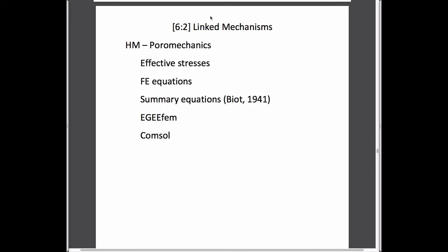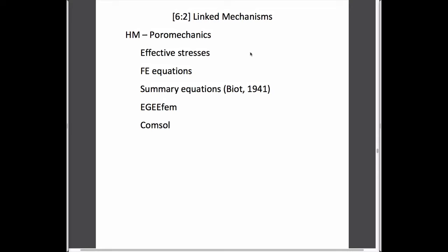The solid system we have is a static one, and the fluids flowing in them potentially change the pressures, and as a result of those changes in pressures, deformation occurs. Deformation occurs because of effective stresses. The law of effective stresses, I guess, is the key, and basically says that total stresses are equal to effective stresses plus some coefficient times pore pressures.